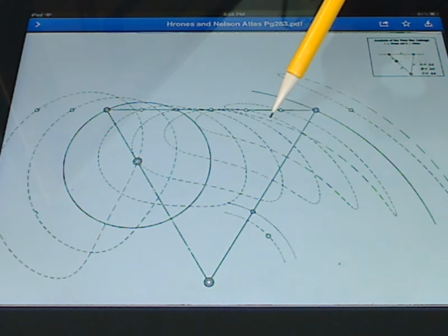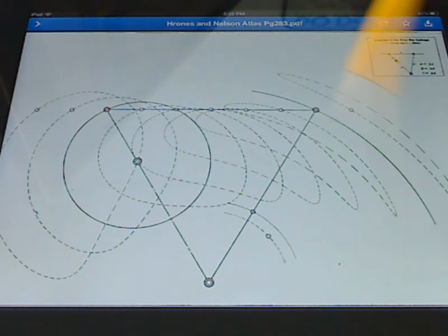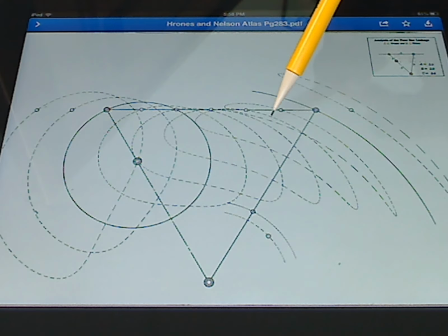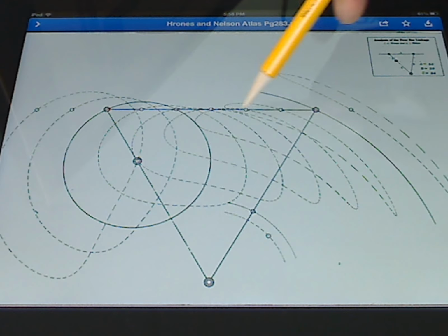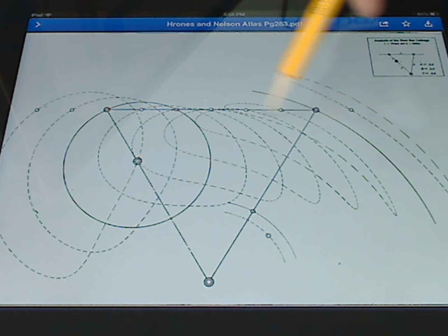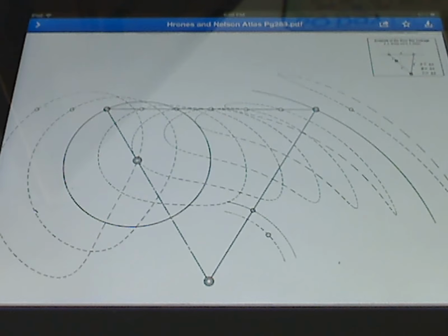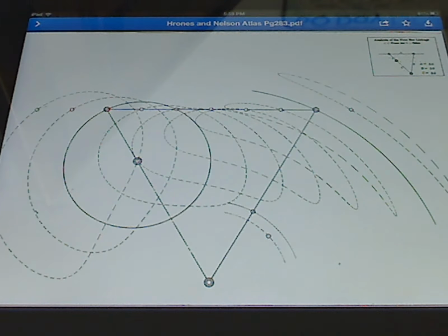These dashes, of course, again represent, you may recall, 5 degrees of crank rotation. And so what we are going for is about 60 degrees of crank rotation in this case, so that says how many of these dashes we want to see before we stop with one of the ones that we want. In this case, we're looking for about 12 dashes, for which we'll be on a perfect arc. And so we can go here and go other places to find our desired curve. And as you see, there's many other curves that we could choose from on this particular page of the atlas.